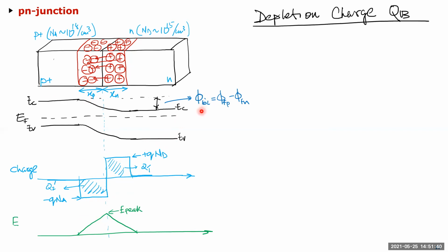So what we're interested in is calculating this depletion charge, right? And this depletion charge calculation is a key calculation we use a lot during our MOS calculation also. So while introducing the PN junction, I decided to introduce how to calculate how much charge is inside it. If you know the doping concentration of a silicon material and they're joined together, what kind of charge is accumulated in this depletion area and what's the length of this charge? Actually, once you know the total charge, you know the length because you divide it by the volume concentration for it.